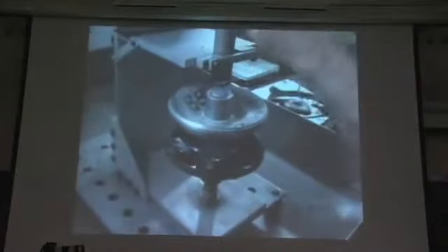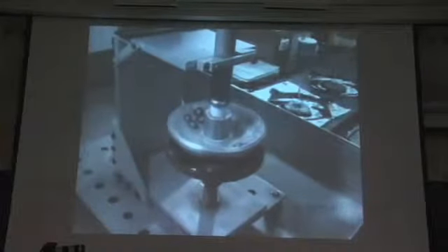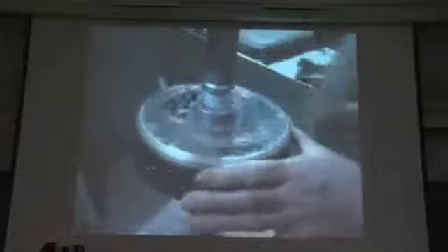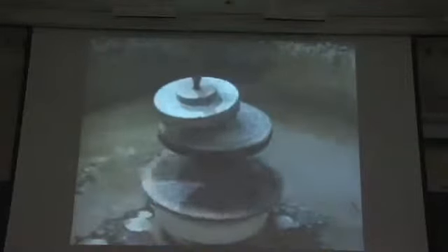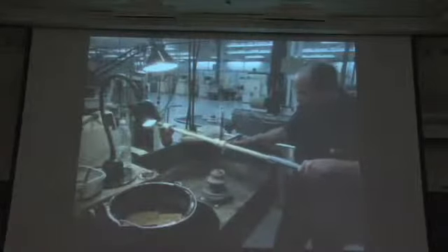A worker picks up a hot aluminum dome called a blocking body. He presses it onto the pitch-covered lenses, and the pitch melts onto it. Dousing it with water causes the pitch to harden, sealing the lenses to the blocking body. The blocking body is now upside down and acting as a holding device as it oscillates on a spinning grinding shell.